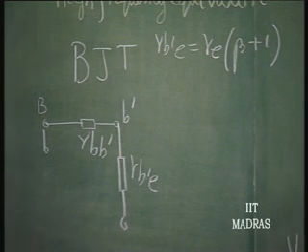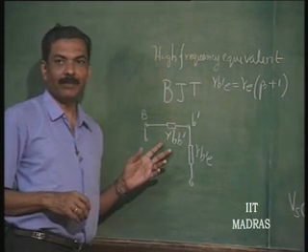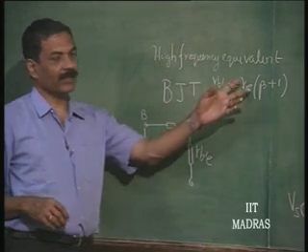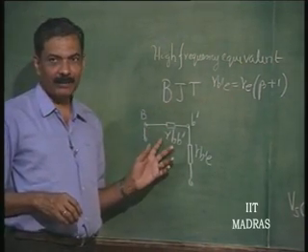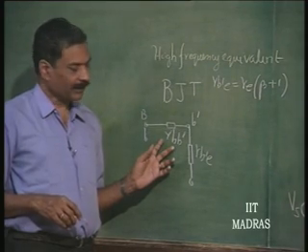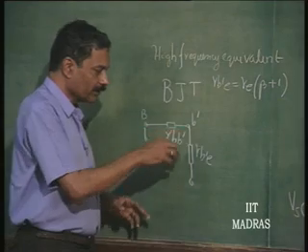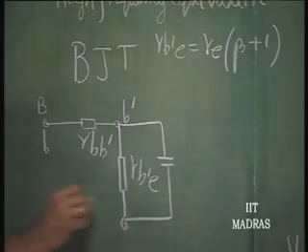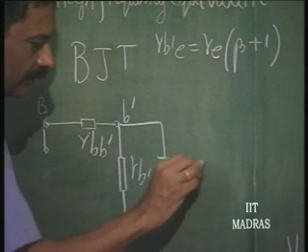This is the normal impedance which we have been using for the common emitter amplifier, except that there is some ohmic resistance of the order of tens of ohms added to that. Since this is of the order of kilo ohms, in normal practice this is always ignored, but at high frequencies you will see there is a visible change in the characteristic, because the capacitance Cb dash E, the junction capacitance, comes directly across the junction. So, this is Cb dash E.